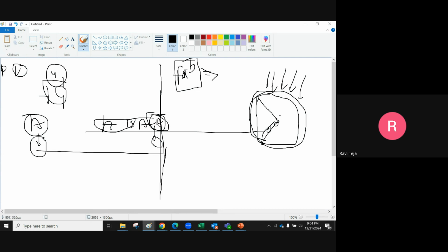That means there might be a chance that this device may turn on quickly because of VT variations, as we have more ions here, more minority charge particles, which are required to turn on the channel. So this device will turn on quickly and this device will turn on slowly. But in the actual operation, what we need is all these devices to turn on at the same time. Due to VT variations, one device is turning on early and the other device is turning on late.